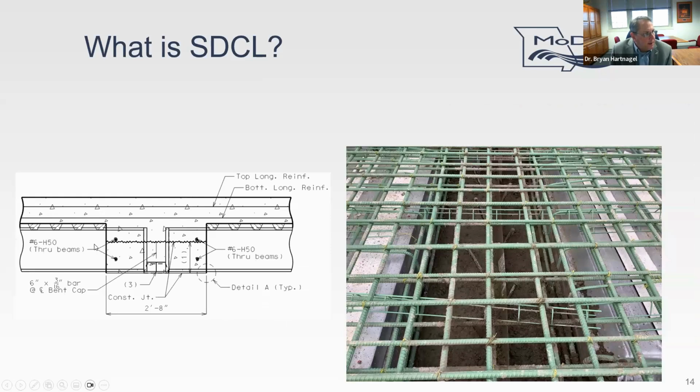We also have a detail that we asked the contractor to pour a little bit of the concrete in the intermediate bends and at the end bends to kind of lock in the girders before we pour the whole slab. There's a thin sheet here that you can see on the plan sheet, and you can see it here in the concrete. And the thought there was it's going to crack here, so let's form the crack with this sheet.